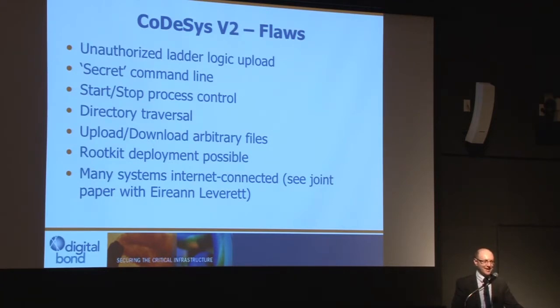You could also retrieve any file from the PLC. Some of these PLCs and RTUs which run the software are fairly complex computers that have full installations of Windows or Linux, so the ability to retrieve any file on the system can actually help an attacker quite a bit. Due to the way that the ladder logic is written, you can upload a special ladder logic file which lets an attacker maintain access to the controller, and it could actually prevent the controller from ever being updated again. So this is actually a rootkit of sorts.